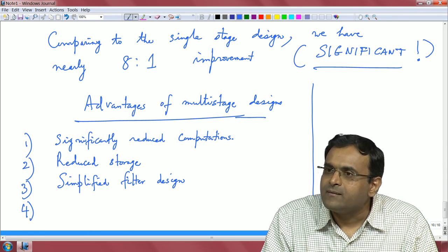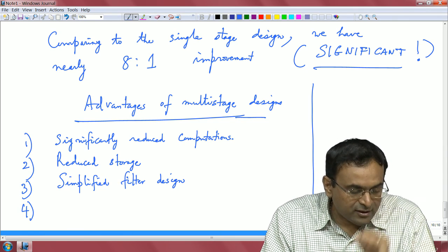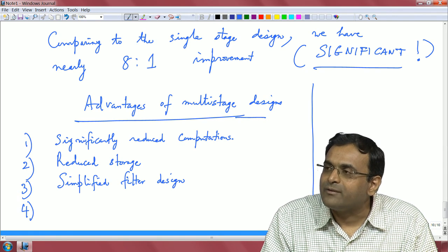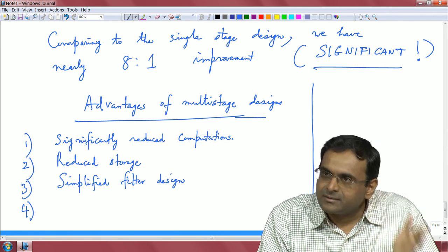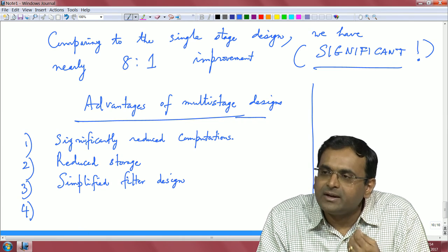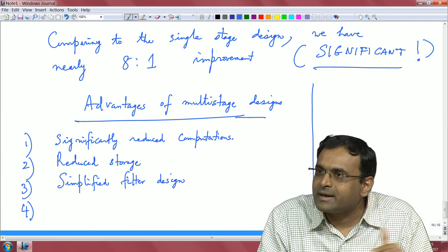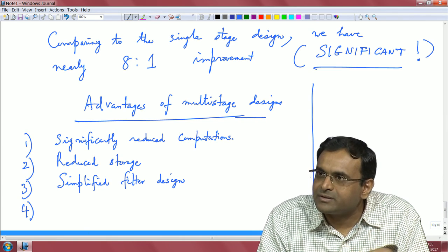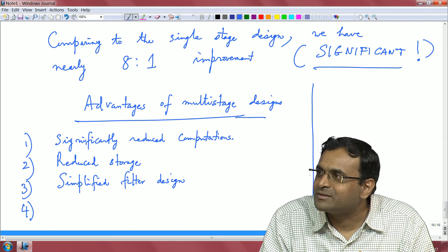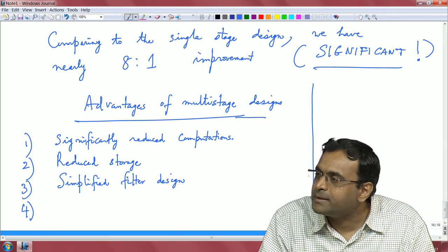So, therefore, when you think about such filters, they are subject to finite word length effects, and if you think about the quantization noise, you have to look at what is the implication of quantization. When you quantize every filter and you take an input noise and you filter it through this filter, it is going to be colored because of this filtering, and the variance also would be higher.